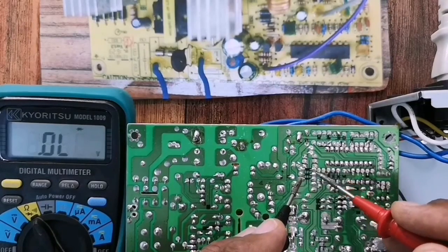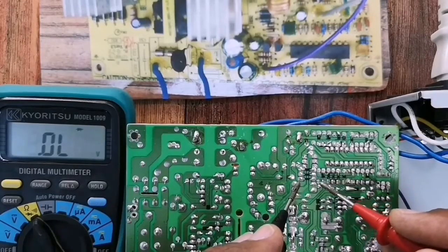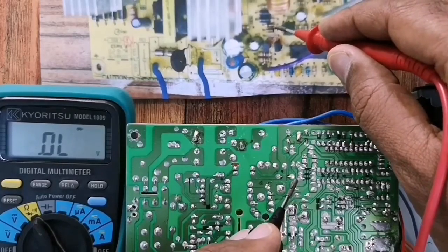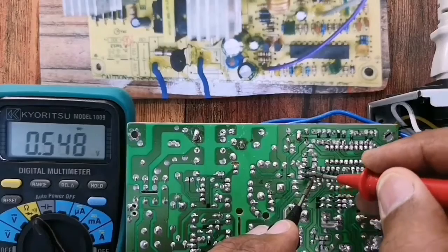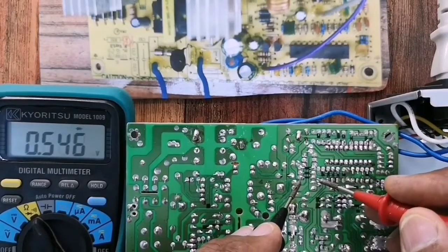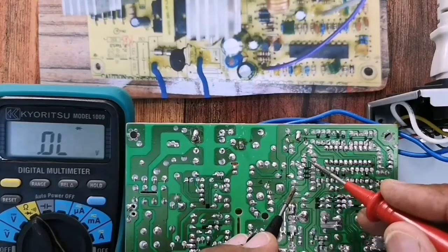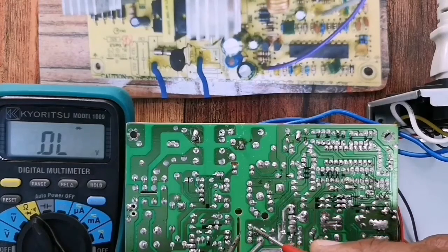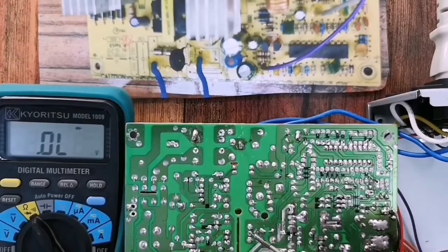Yes, also okay. The emitter is connected to ground through 2 diodes. Let's check the diodes on circuit. Both good as well. The collector side from both transistors is connected all the way to the transformer windings, nothing in between.